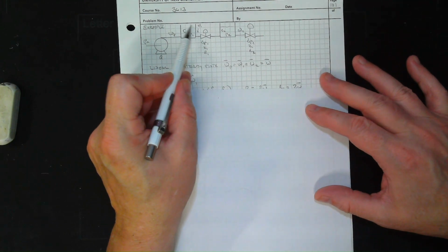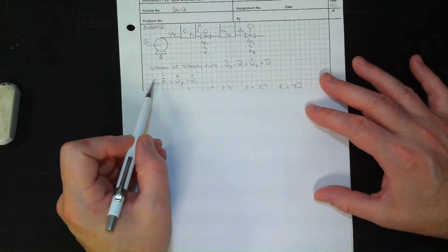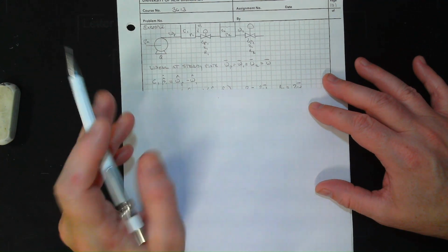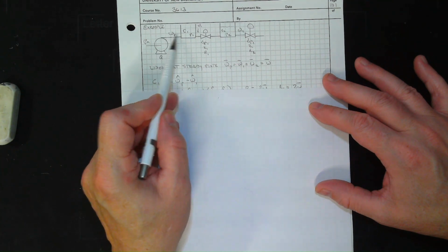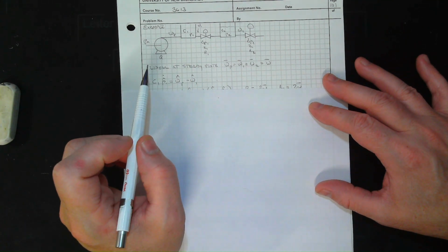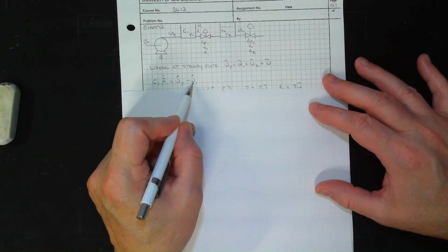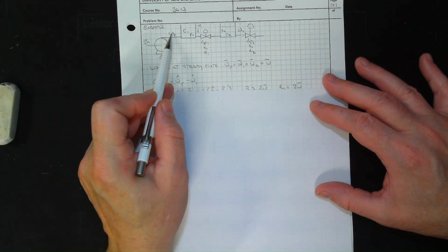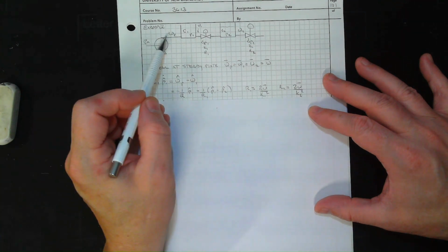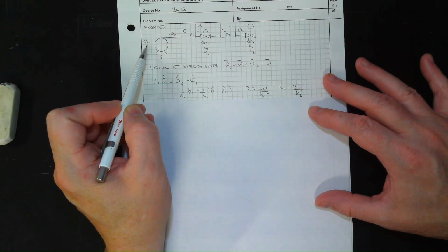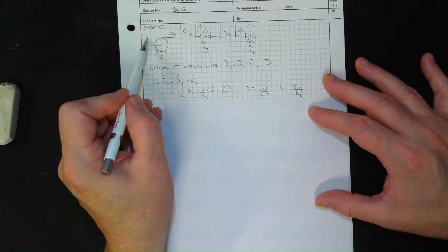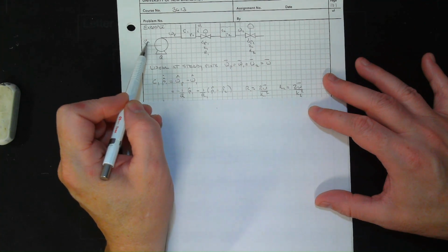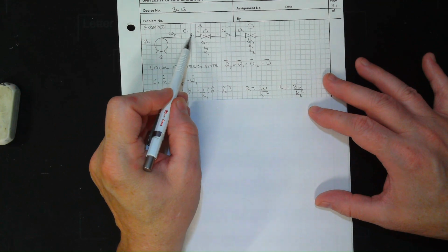Okay, so let's look at this first tank here. So we have C1, P dot, but it's the perturbation version, but that's fine, will be the flow in, perturbation flow in minus perturbation flow out. Omega P hat minus omega 1 hat. That's all we have to do. Now, what is omega P? Well, that'll be driven by pressure, and we are stepping up the pressure, but it's from 0. We're just looking at gauge pressure, so the steady state we don't care about. So we're going from 0 to P1 hat.